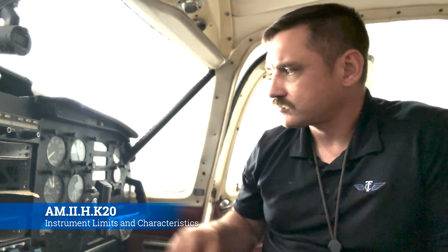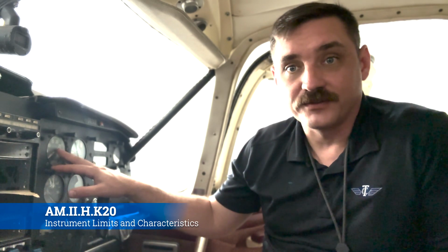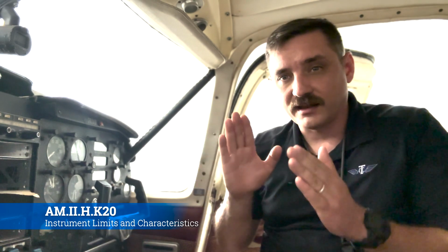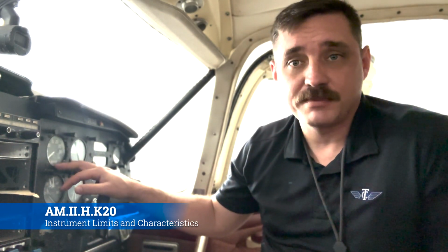Now, as you grow as a mechanic, you'll start to see that, hey look, the mag drop on this plane is a little bit low, or a little bit too much. But I'm also seeing this other indication over there, and that helps me triangulate what could potentially be happening. Maybe there's some sort of electrical failure. Maybe the points on the mag are off, or who knows what the problem is. The point being is that the engine will tell on itself if you listen to it, and the way we listen to it is by paying attention to the engine instrumentation that we get in the cockpit.